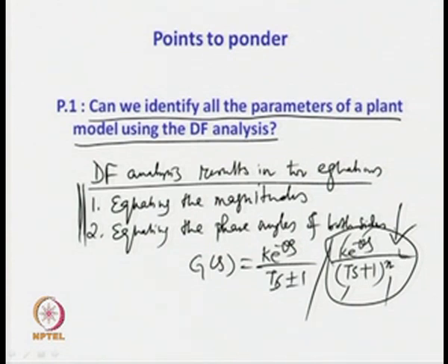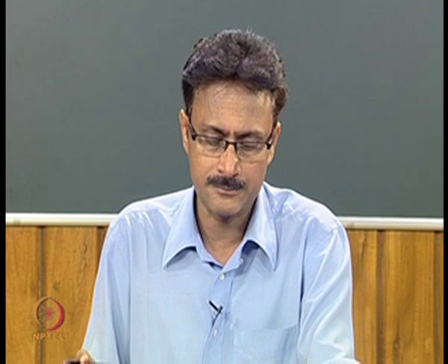So, describing function analysis has this major limitation that we have to use simple plant or process transfer function models for identification of system dynamics or plant dynamics using online identification.